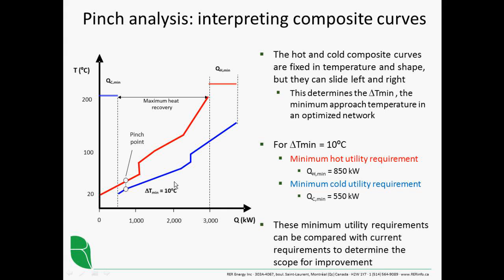However, there is a downside to that, of course, and that is as we shift that cold stream further to the right, it makes it easier in terms of smaller, less costly heat exchangers, but we're increasing the amount of this cold composite curve that is not overlapped by the hot composite curve. So that increases our hot utility requirement.